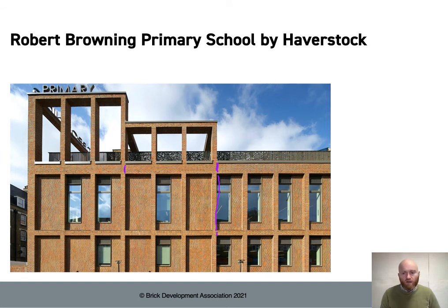And I know it's not really something you want to be thinking about as designers at the concept stage, at the beginning of designing your building, but just some clever setting out of brickwork dimensions can really minimize the need for any overtly in-your-face movement joints.